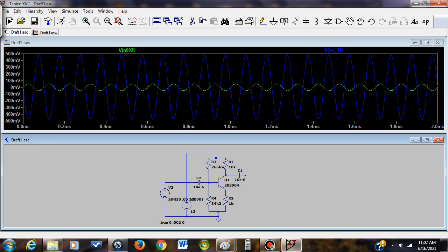And granted, again, because it doesn't affect the input impedance of the amplifier. So if you're going to attach one stage after another, we really need to have a high input impedance to each of the stages. So by having at least 1K as your RE value, you're ensured to avoid having to load whatever the signal is being inputted.